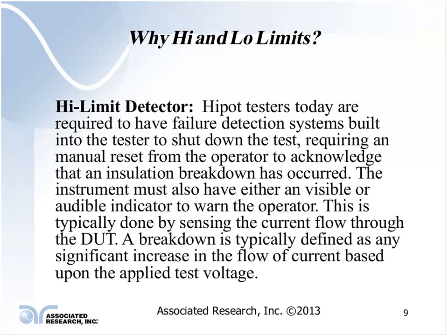Why high and low limits? Hipot testers today have multiple failure detection circuits. Years ago, we added the low limit circuit to the tester as a way of verifying that the test was actually being performed on the product. This came about as a result of a visit to one of our customers.